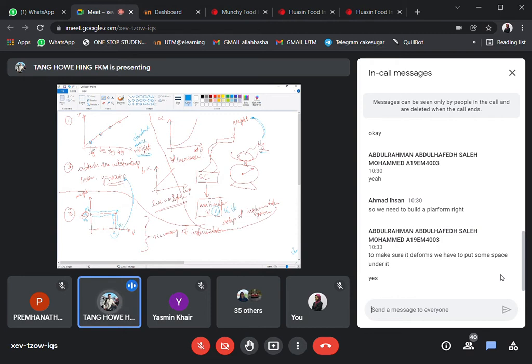So in that case, because you know the weight and then you plug it here, you get the readings from your Arduino or multimeters, then you get the voltage. So in that case, you can get this kind of plotting. Okay, but of course, you can also repeat this process several times. So in that case, most of you will get this and this and this and this. And in that case, you can average it and then eventually come out with these lines.